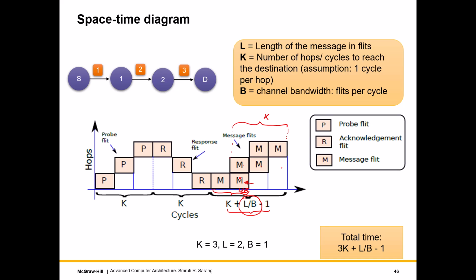In the case where a flit is an atomic unit and it is taking multiple cycles, we may not want to pipeline flits within a flit. So if B is 0.5, then instead of 1, this will become 2 over here because there will be a double counting of 2 cycles. But let's not make this formula more complicated.